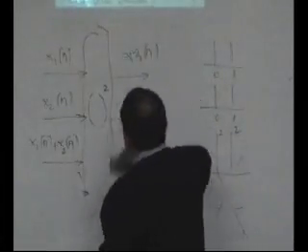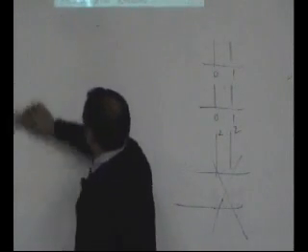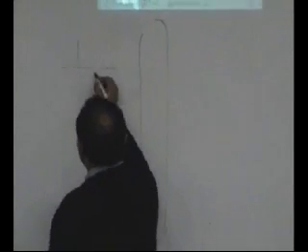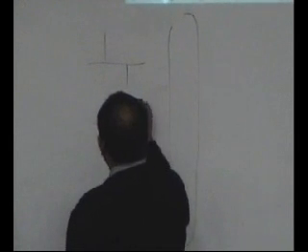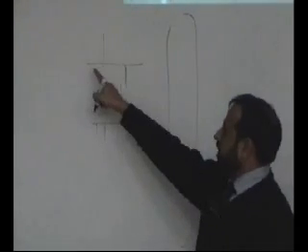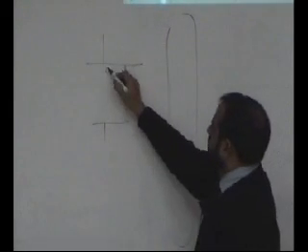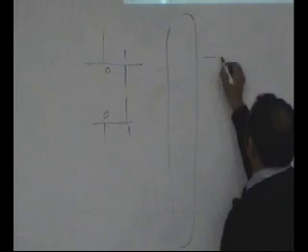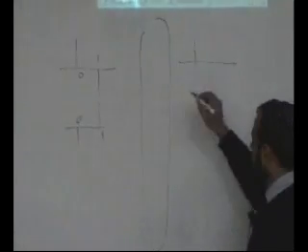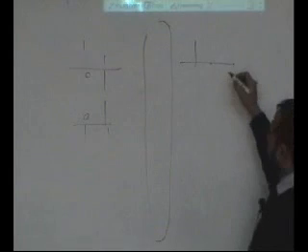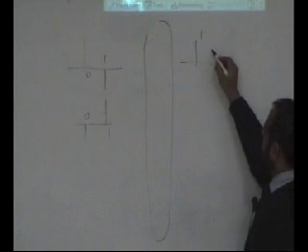And so this is one property of linearity. The operation which I performed earlier, where you add a sample to the previous sample, is linear. Let's check that. So this is a system where, let's do the same example. Here, add it to the previous sample. Okay, so 1 plus 0 gives you 1, minus 1 plus 1 is 0, minus 1 plus 0 is minus 1, so this is what you get.